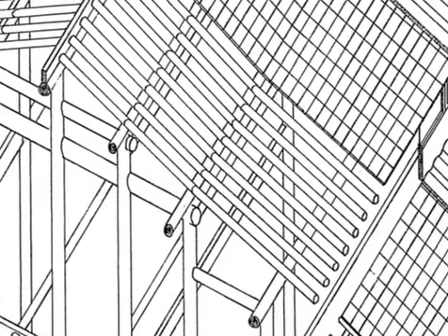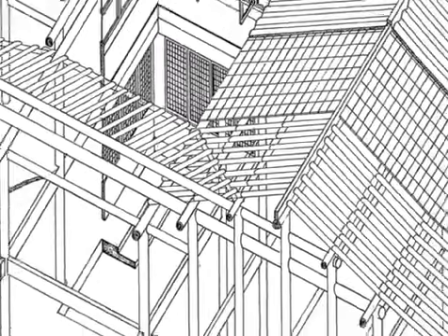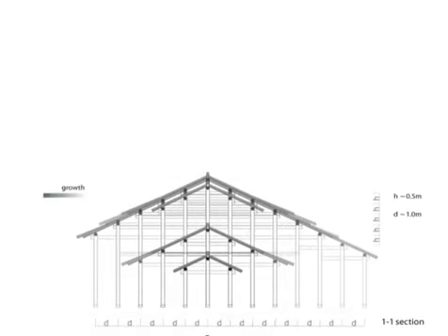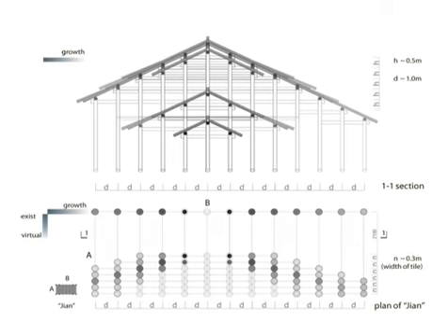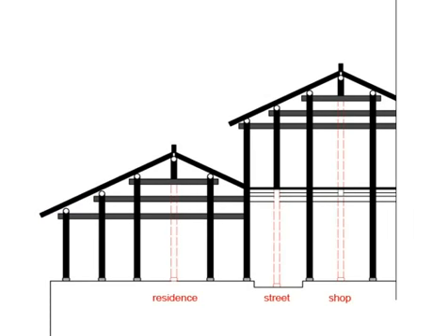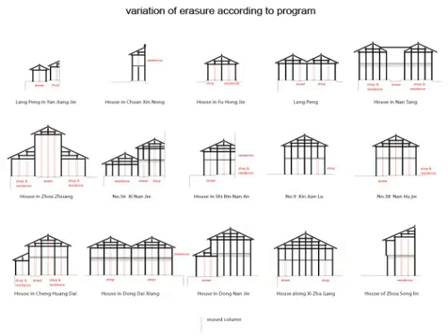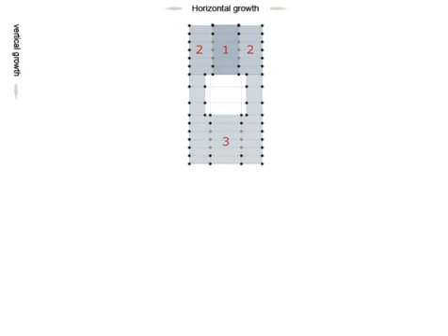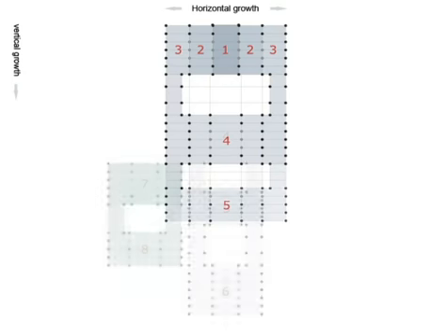In the canal towns of the Jiangnan region, a lightweight structural system called Chuandoujia is often used. The structure is composed of roof purlins, which are directly supported by the columns below. By erasing some of the supportive columns, different programmatic demands might be accomplished through the various spatial sizes created. The whole structural grid can readjust itself by combining with systems of Tailiangshi as a hybrid structure. In the formation of a house, the structures are repeated through a room module called Jian, and generate two-dimensional growth in order to accommodate various programmatic, social, economic, and environmental demands.